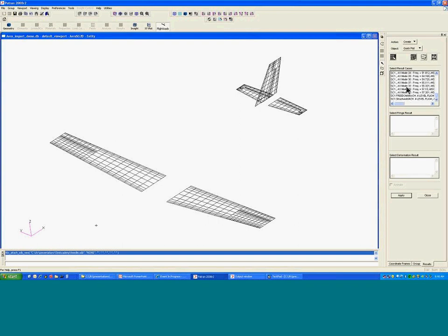So now I still got all those mode shapes from before, but now I've got 2 additional cases that were brought in. The first case is the results available on the aerodynamic mesh. The second case is the same results, but for display on the structural mesh. We've got them separated for simplicity. So I can come here on the aero mesh and simply look at the displacements. Now, this particular solution was a static aeroelastic solution due to a 1G level flight condition of this little aircraft.